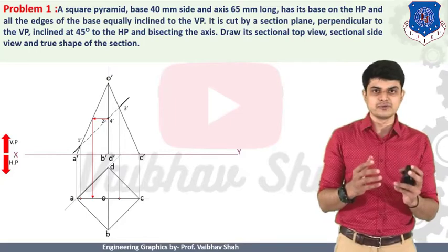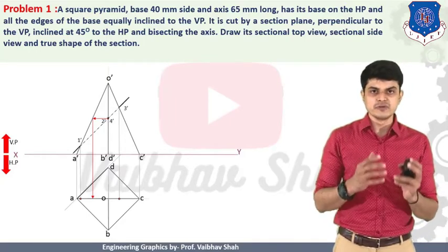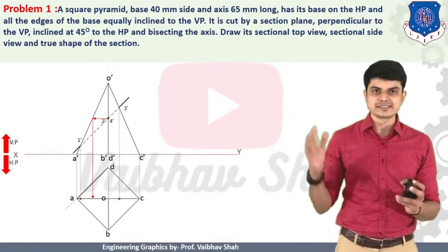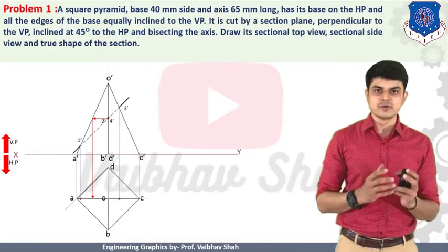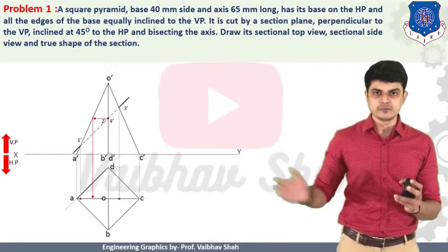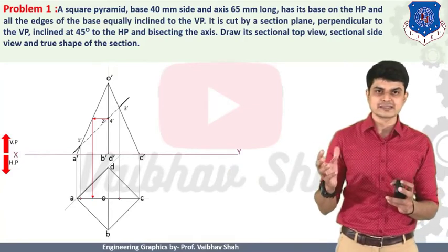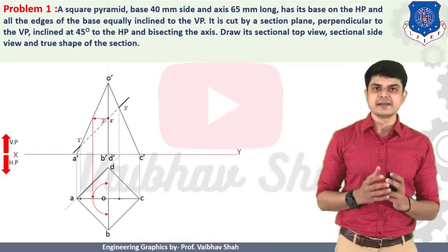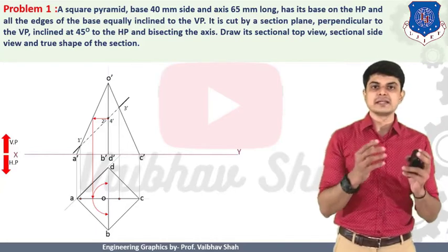Now we should give the point back to the lines to which it belongs. So take your rounder and put it at the center point O in the top view. Then take the radius from center point O till your red arrow on the OA line in the top view. Thereafter, keeping that radius in your rounder, draw two arcs like this. You will have two points transferred onto your OB and OD lines respectively. So now your point is finally transferred to your OB and OD lines.